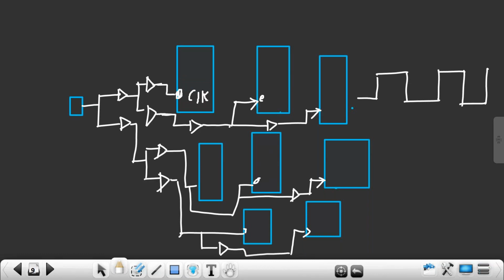So one thing is you should not use long nets. Long nets will lead to more transition. If more transition, the clock signal will take more time to rise and more time to fall. So here I have a fall pulse. This fall pulse is good, no issues. But the rise pulse is very small. The on time is very small, but the off time is huge. Small on time cannot be accepted.